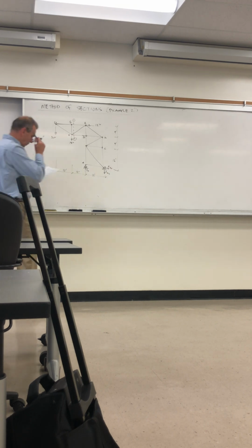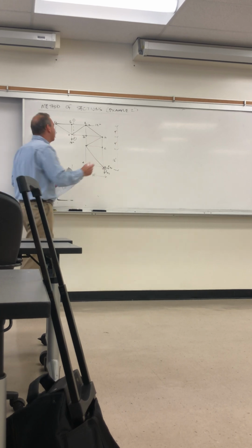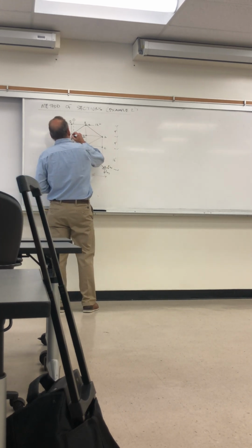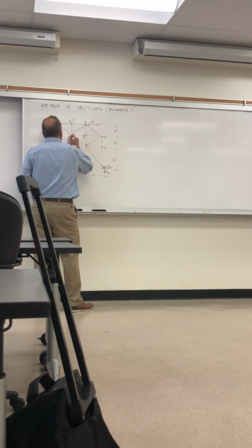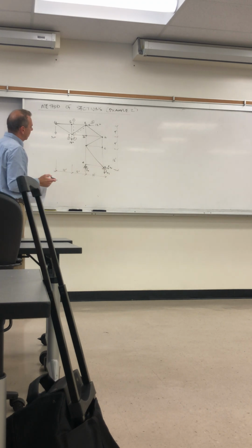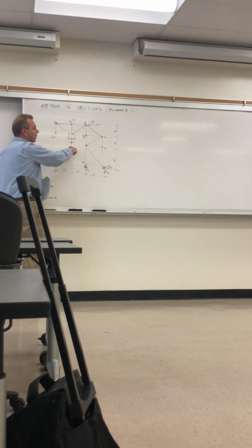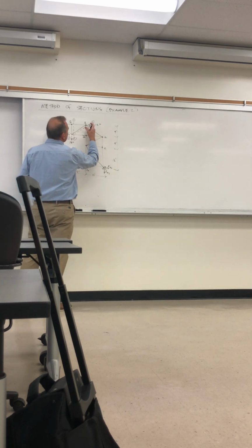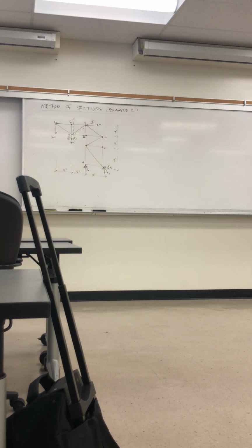Section 2-2 is just to the right of E and H, so it's a diagonal cut here. Notice in section 1-1, we're going to need to include the 18 kips. In section 2-2, we're going to need to include that 12 kips here. That arrow is right at the joint, so it's just to the left of the dotted line.